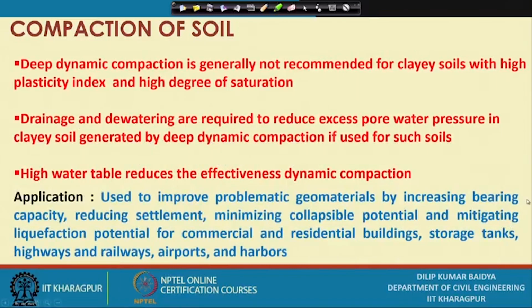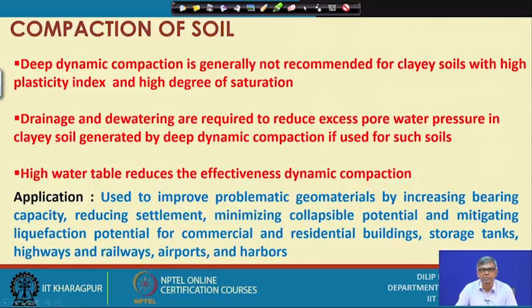Now, deep dynamic compaction is generally not recommended for clayey soils with high plasticity index and high degree of saturation. If it is a soft soil and a heavy weight falls on it, it will just displace, it will not compress. If this much compression happens, a similar amount will displace upward.